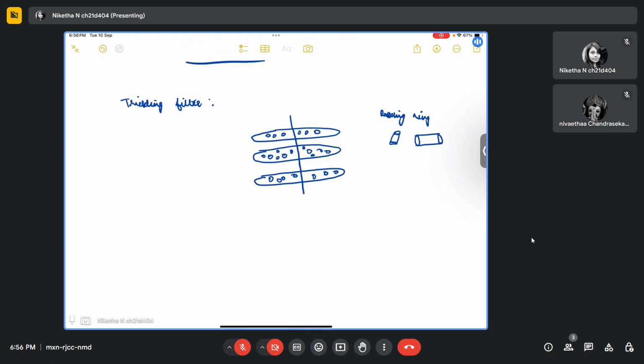And over this, when you pour wastewater, you can have many ways by which you can do that. You can have some sprinklers on both sides. So the sprinklers will sprinkle wastewater here. When this happens, the wastewater will trickle through, or it will pass through and go to the next layer. From this layer, it will come to this layer, and finally it will come out. So this thing is called trickling.